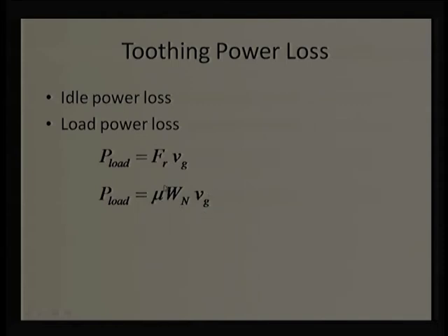The question comes, will mu be changing really, or is it going to be constant? Will Wn change or will it remain constant? These two are important aspects. In fact, if you take my words, mu cannot be constant. We know the loading points are going to change, the applied load is going to change. It may vary from 0 to kilonewton load.